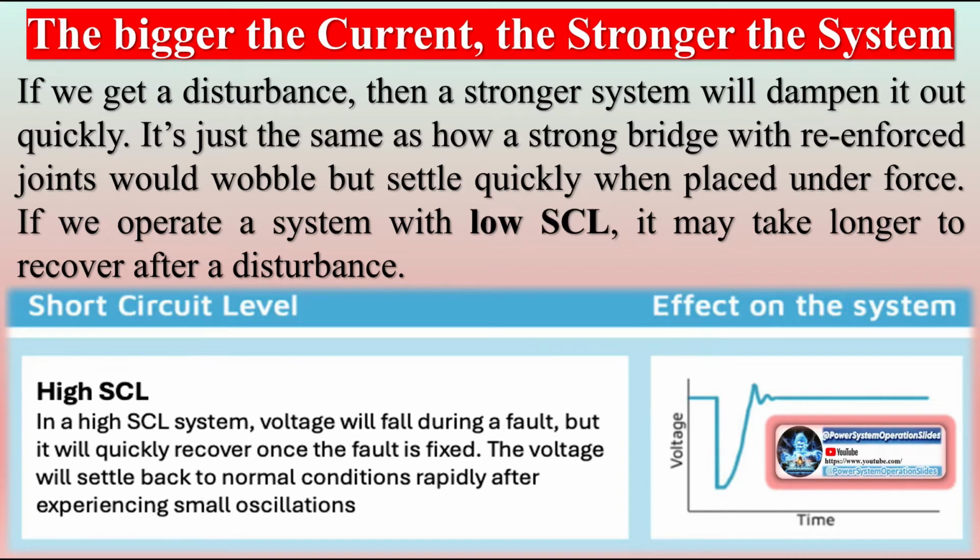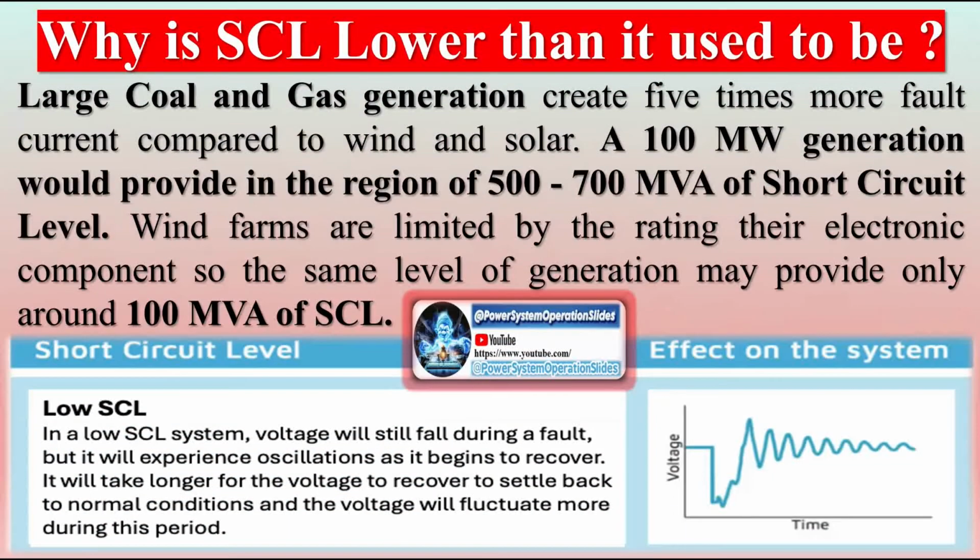Fault current calculations are necessary to properly select the type, interrupting rating, and tripping characteristics of power and lighting system circuit breakers and fuses. Results of the fault current calculations are also used to determine the required short circuit ratings of power distribution system components, including bus transfer switches, variable speed drives, switchboards, load centers, and panel boards.